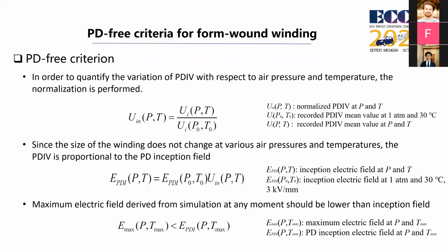Now we obtain the PDIV values with respect to temperature and the pressure, but how to correlate the experimental results with local electrical field values that can be obtained from simulation? Then the PD-free criterion is proposed. The key is to correlate the PD inception field with experimental results.